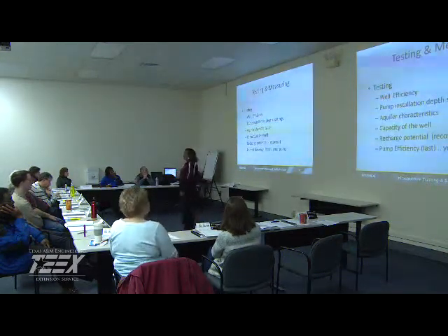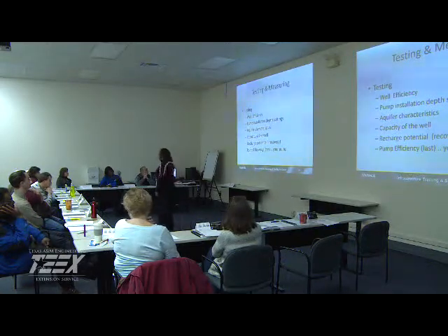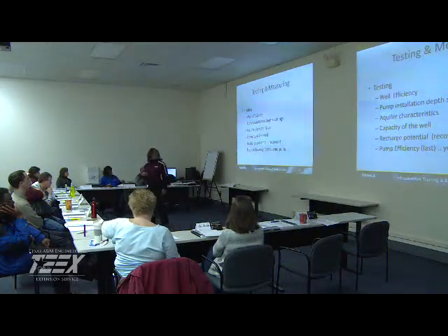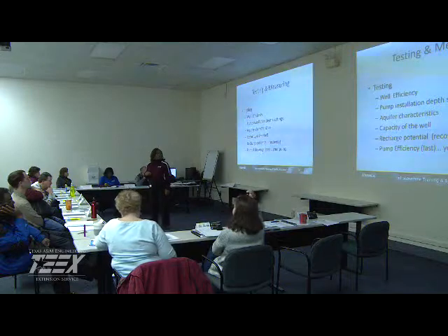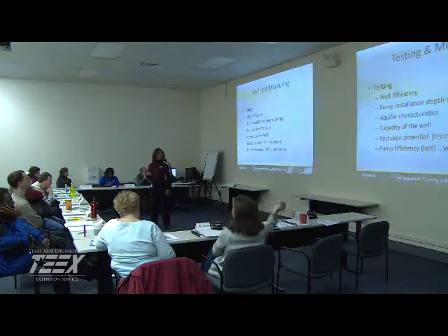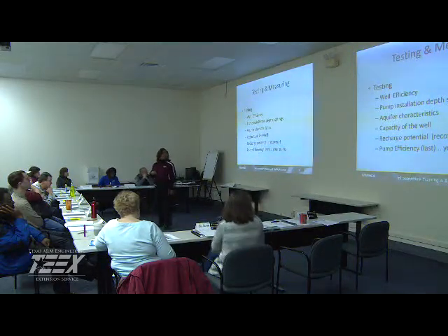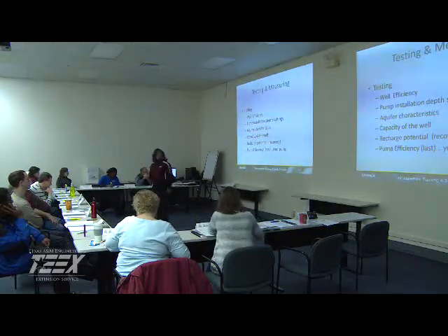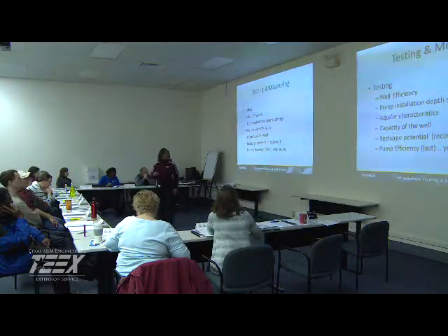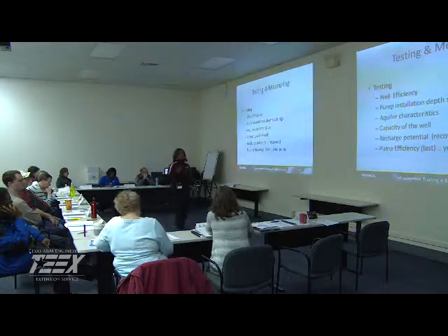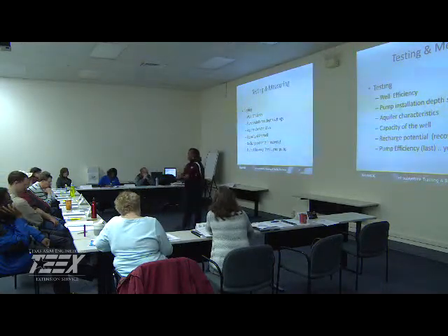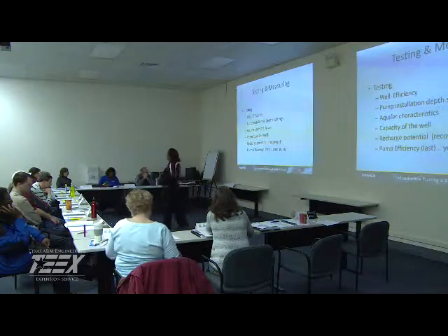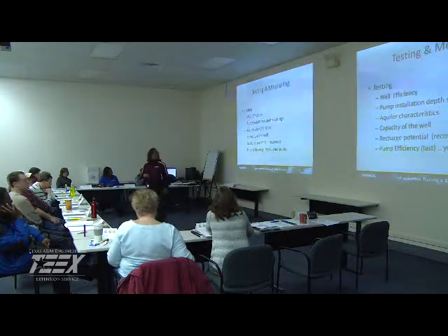And then you want to make sure you go to the next step and do the testing. We're testing for efficiency, capacity of the well, and pump efficiency. What's the recharge potential, the recovery? What do you expect? How many gallons per minute? All of that. Aquifer characteristics. Remember the chemical and physical characteristics of that, because that's something that will be ongoing every 3 years.